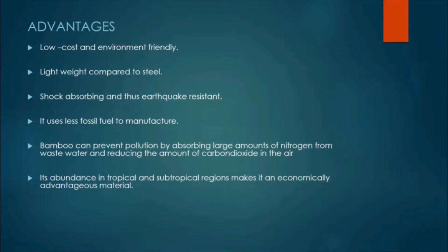Bamboo can be utilized for permanent and for temporary construction. The composition of the fibers in the walls of the bamboo allows it to be cut lengthwise or cross-cut in pieces of any length, using simple manual tools like the machete. Another advantage of building with bamboo is that it can be used in combination with other types of construction materials, like reinforcing material for foundations.